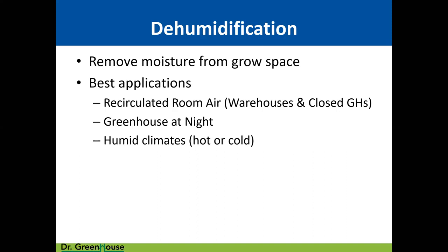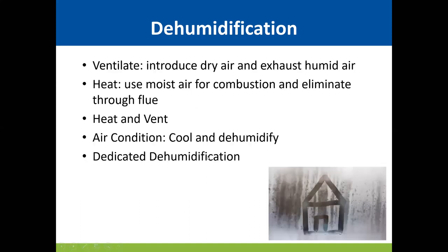Okay, dehumidification. We are removing moisture from the grow space, okay? Best applications when we're recirculating the room air and we're not bringing any dry, fresh air from the outside. Greenhouses at night, when it is cold and dry outside, we can relieve some of that moisture. And of course, if you're in a humid climate, and we want to remove moisture.